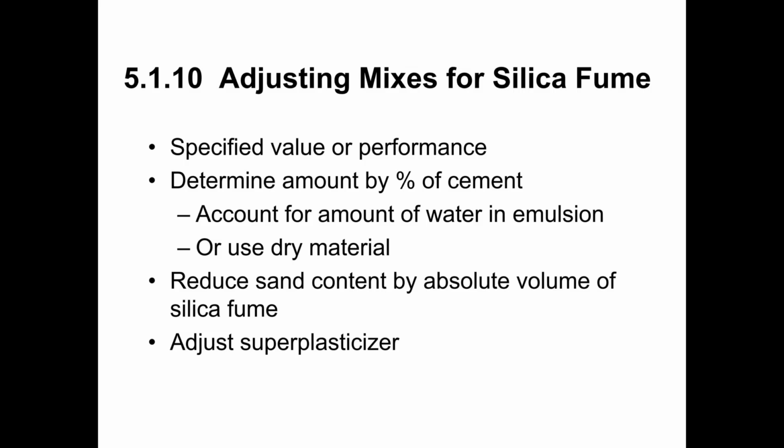All right, so since the specific gravity of the silica fume is different than the specific gravity of our sand, then that means we will be taking a certain weight of sand out, but adding a different weight of silica fume so that the volumes are the same.